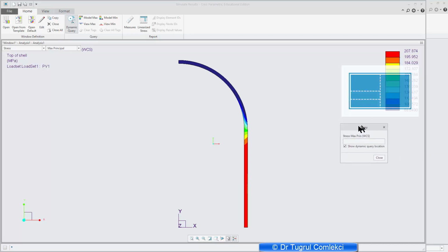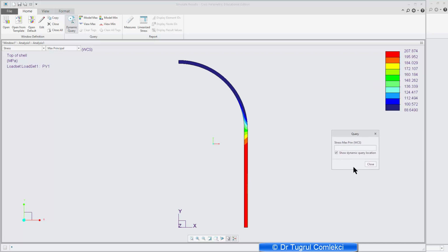And what you'll need to do is use the thin wall shell theory, thin wall pressure vessel theory, to look at what is a theoretical stress for the spherical bit and the cylindrical bit of this pressure vessel.